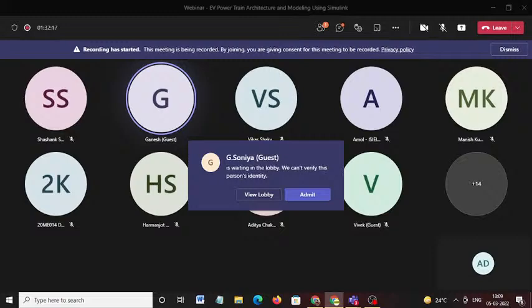But the problem here is whether your throttle is responding properly or not. As I said, your throttle angle plays a very important role in cruise control mode. One issue I see is that when we activated cruise control, it went directly to 50 kmph and was not coming back. This comes under signaling issues.